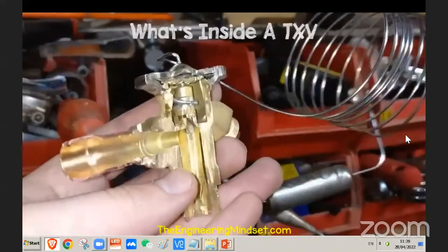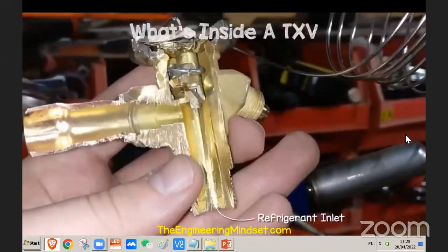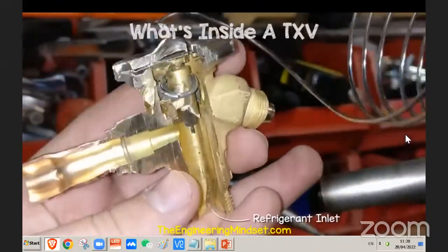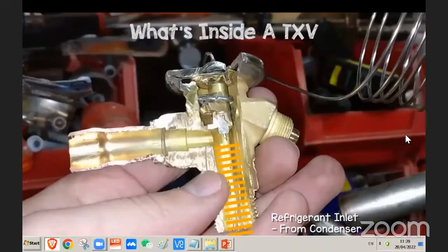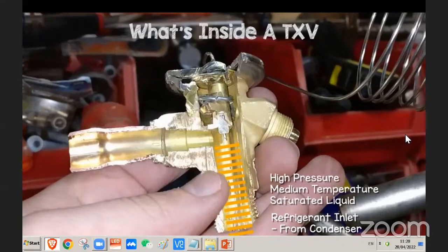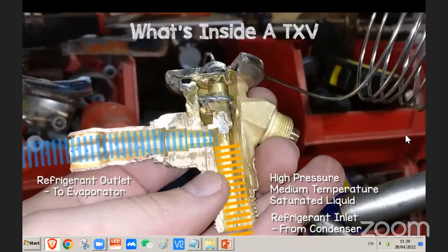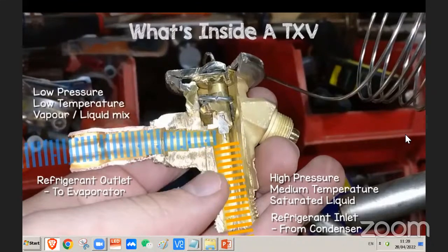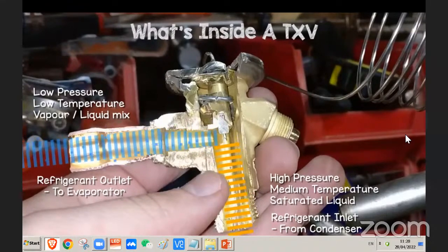So we have the main body which holds everything together. We have the refrigerant inlet coming in from the bottom of the main body in this vertical pipe, and then the refrigerant outlet on this horizontal pipe. So the refrigerant comes from the condenser and enters the valve body via the inlet. It enters at a high pressure, medium temperature saturated liquid. It then passes through the valve body, and when it leaves, it exits the valve through the outlet and will now be a low pressure, low temperature liquid vapor mixture.